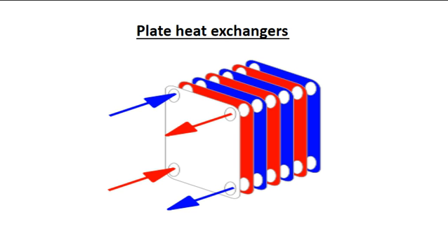When used in loops or open loops, these heat exchangers are normally of the gasket type to allow periodic disassembly, cleaning and inspection. There are many types of permanently bonded plate heat exchangers such as dip brazed, vacuum brazed and welded plate varieties, and they are often specified for closed loop applications such as refrigeration.